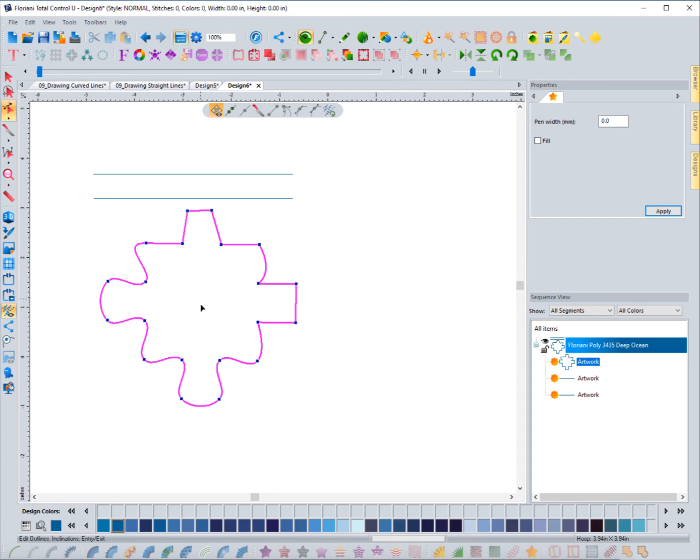So what else can we do? Let's say that I no longer want this to be a closed shape, because I want to actually have no line in between here, because maybe I'm going to add something to it. So what I can do is click on this node right here, and let's just look at what our options are up here. We have split line, we have a slice tool. What we're going to do is split the line. Now I can click this icon, or I can right click here, and I can choose to split the line right here. Okay, so it exists in both places.